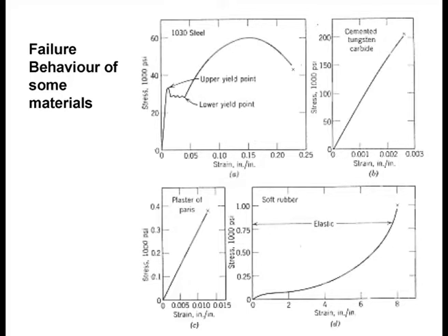Okay, I'm not saying that you will not hit that kind of scenario in practice. Sometimes when you have very cemented soil, for example, if you cement treat the soft soil, when you deep mix the soft soil with cement, and then you start to make a tunnel through that material, there is a chance that you may get a crack on the crown of the treated soil.